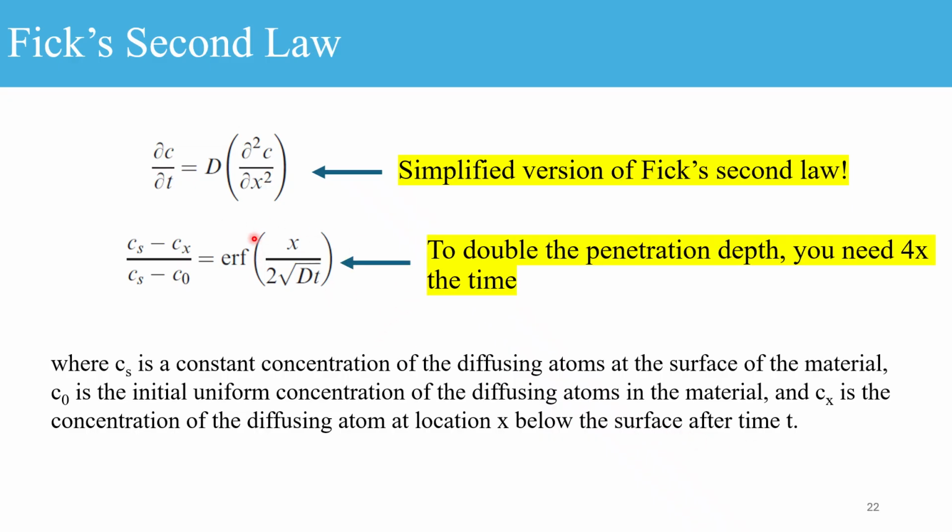From this equation, we see that to double the penetration depth, you need 4 times the time of diffusion. So you need to allow enough time for the material to really be penetrated through its depth by the diffusing species.